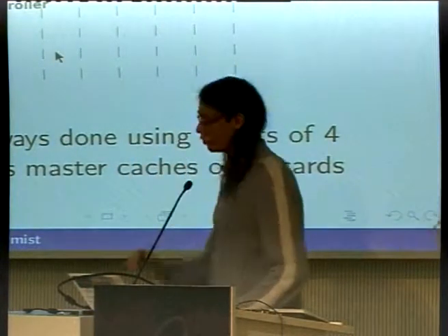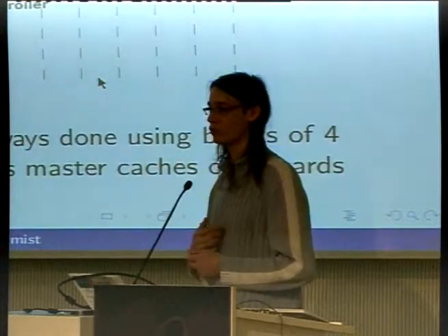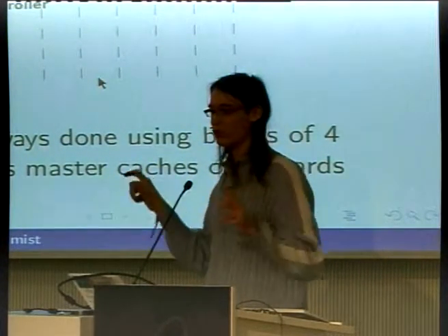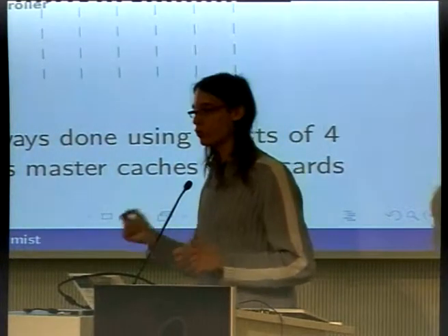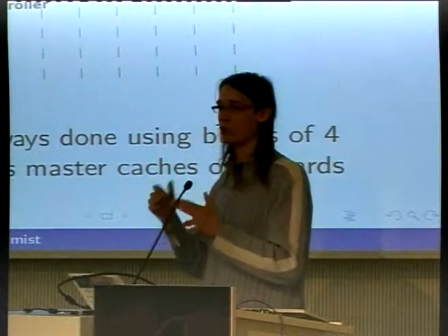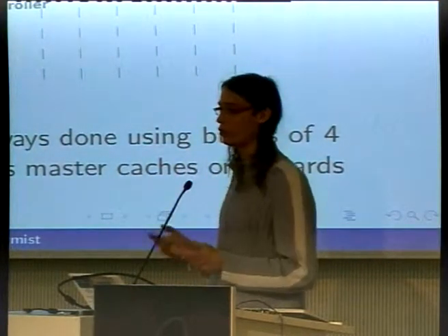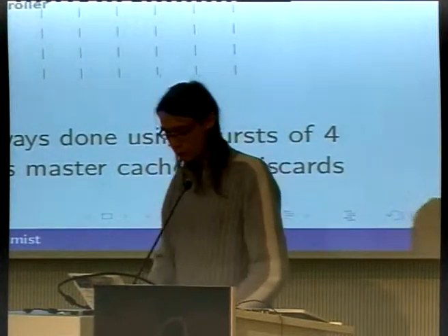But to take every slot, you need to issue also a read command at every slot. And so you need to predict perfectly the address sequence that you put into the SDRAM. And on top of that, you have other problems like memory refresh, or sometimes you have to change rows in the DRAM array. But well, these are more technical points that I'm not going to cover today. I will just explain this.